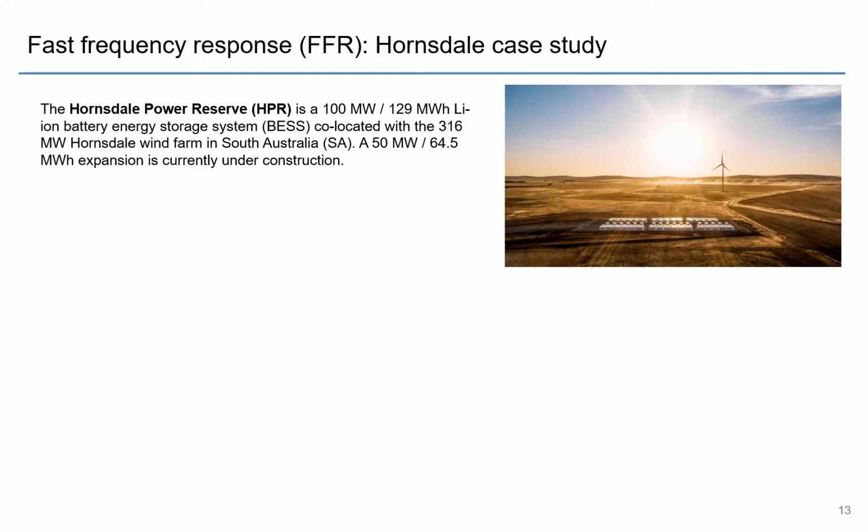By way of example for an FFR is the Hornsdale Power Reserve, which is a battery energy storage system located in South Australia. It's a 100 megawatt, 129 megawatt hour lithium-ion Tesla battery storage, and it's co-located with the 316 megawatt Hornsdale wind farm.